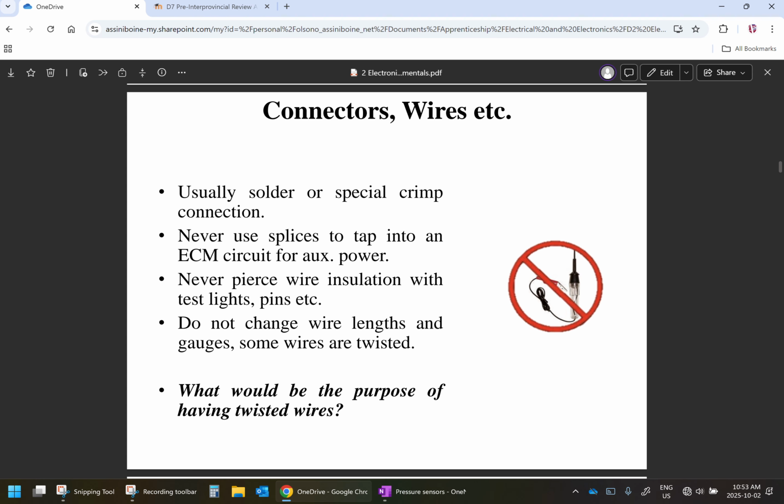It can change the resistance of the wire, and if we're talking about wires that have very low voltage and current going through them anyways, data carrying wires, that can cause data corruption. So we have to be very careful about doing that. Okay, that's one reason. And the other reason is if you have a couple of wires that broke at a certain spot, why did they break in the first place? Probably flexing, vibration, work hardening, and then they broke, right?